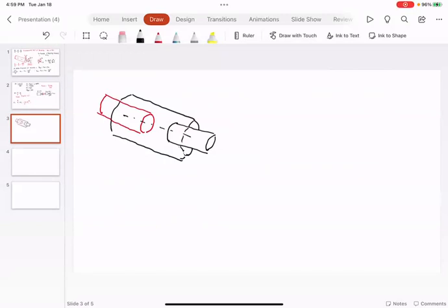But there is a difference. If you look at the stepper motor attached to the lead screw for the 3D printers, the power transmission requirements are not very high. So what you have is a simple set screw. You will see a screw here that goes through the outer sleeve and then attaches to the shaft, or there could be a cutout on the shaft that is called a D shaft. So rather than a circular shaft, there is a D. That way you can attach it more securely.